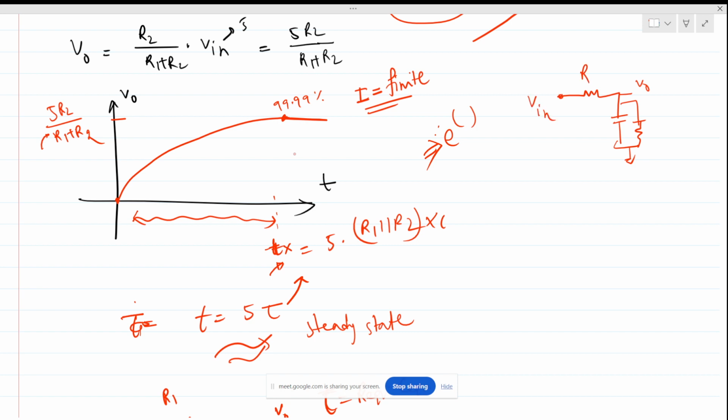For a zero, we know the V out will be zero, right? Actually, in the circuit there is no zero, and I am coming towards it. We know V out will be grounded, so this will be a short circuit to the ground. Is there any storing element here? Actually, this capacitor is short circuited, as both of its terminals are grounded, so it becomes a dead element. So the equivalent circuit will look like this.